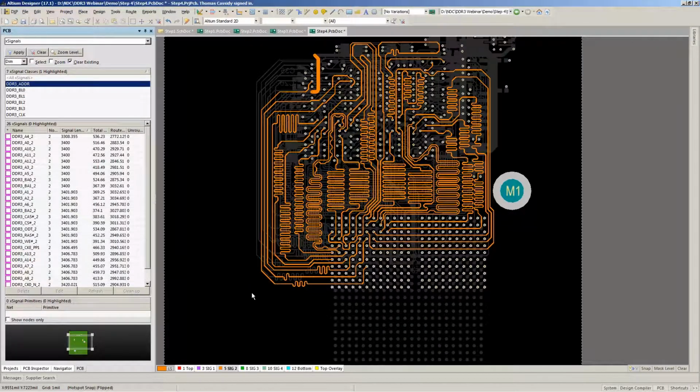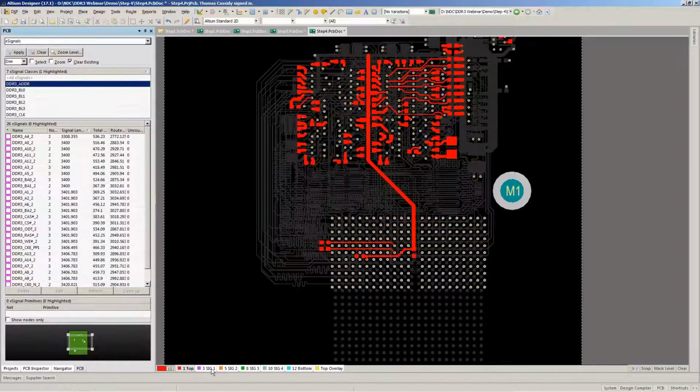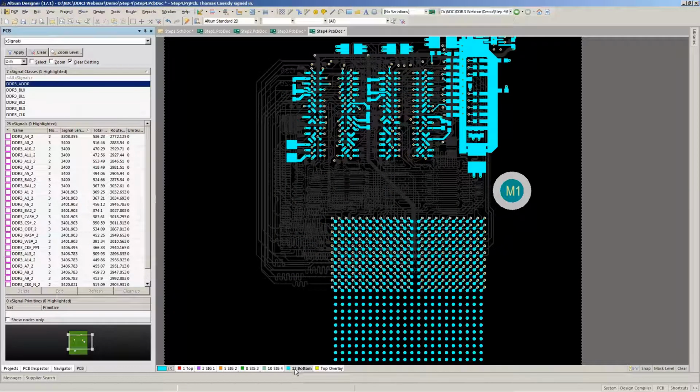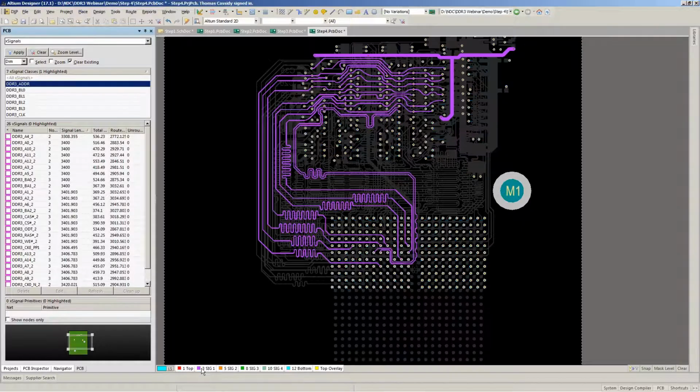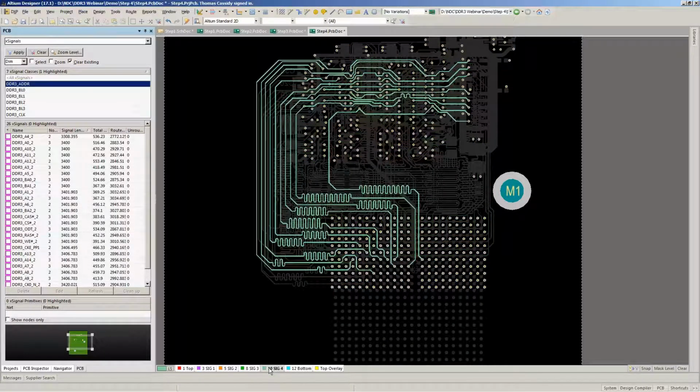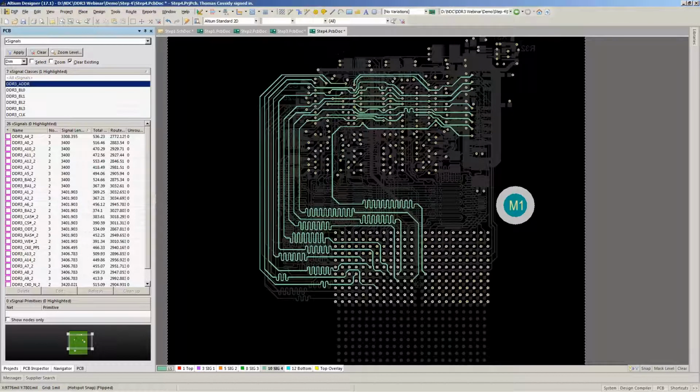One other quick point, as Sean mentioned, you can see this is the top layer and this is my bottom layer. I was able to route all of the other signals on 4 internal strip line layers. So I am very confident that the timing I'm generating, the delays I'm generating with length is pretty consistent between signals. So I don't have to worry quite as much about different dielectric constants affecting my overall timing. So I think with that, I am pretty much done. It was a very quick overview, obviously not how to do it, but showing you the possibilities.